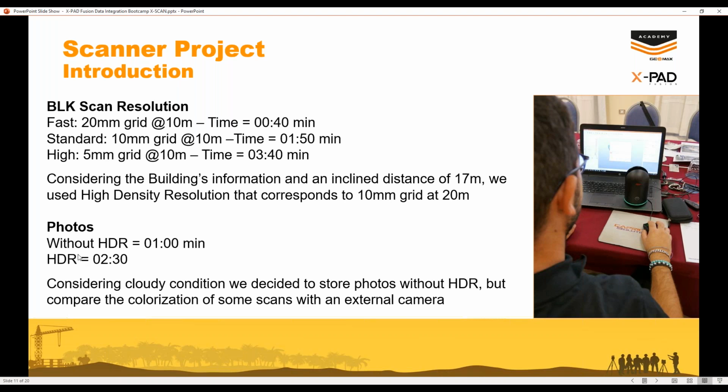Another possibility that we can set for the laser scanning is to also acquire photos, with 2 different types of photos. Without high dynamic range, the photography time is about 1 minute. Using the best resolution for the photos, high dynamic range, the acquisition time for the photos is about 2.5 minutes. But considering the cloudy weather conditions on that specific day, we decided to use the low dynamic range, so without the high dynamic range, only 1 minute of acquisition during